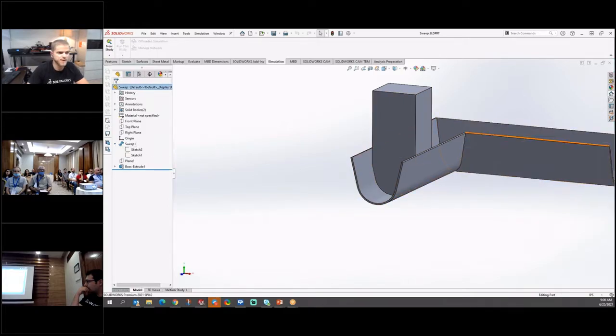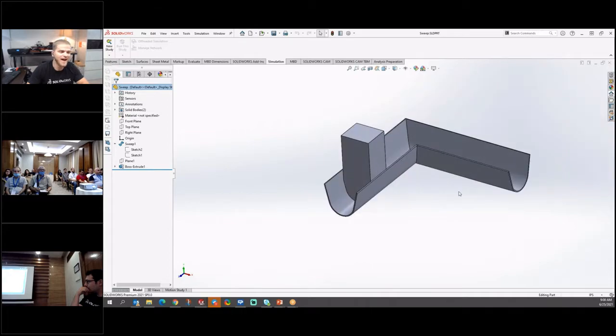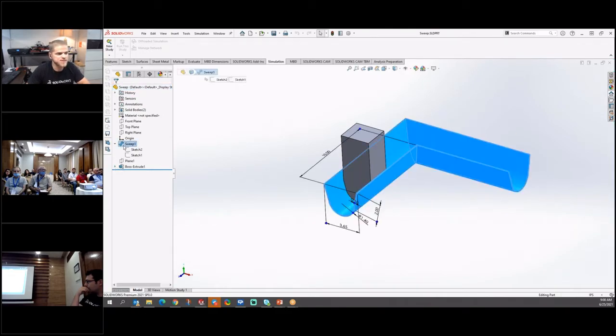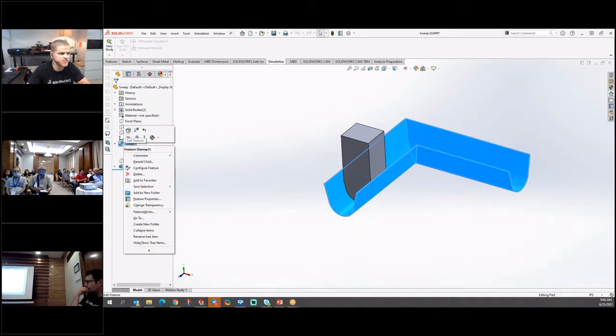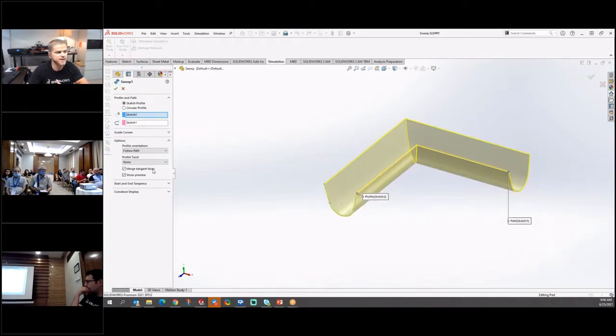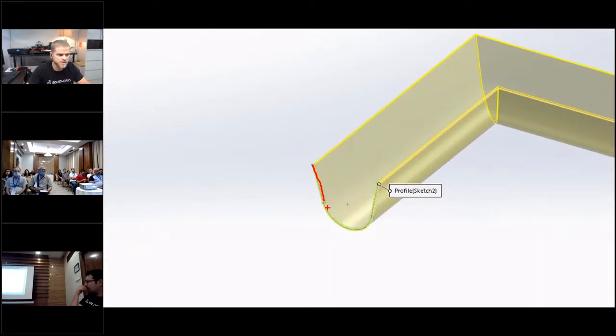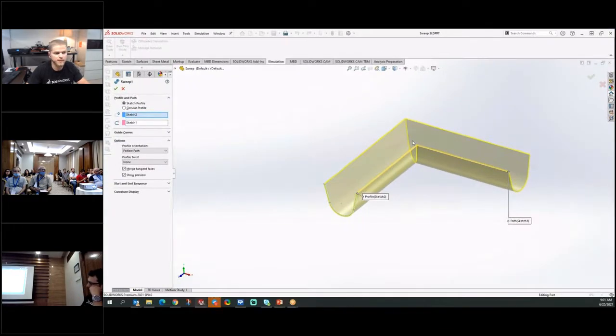And this sweep example, the question from the customer was not this file, right? I have to recreate this with sample files. This isn't the customer file, but they're taking a boss extrude and extruding it up to this sweep here, all the way up to this swept surface. And if I edit this feature here, it's a plain old swept sketch. There's nothing too complicated about it. It's 3 sketch lines. So we see 1 segment, 2 segment, and 3 segment sketch line that are being swept